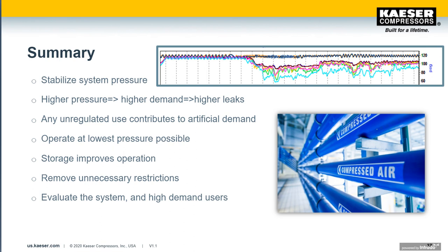Remember that pressure profile graphic that we showed you? Storage is not only going to provide you with better compressor operation, but could also provide you with better operation down there at the point of use. Remember that location of storage does matter. And if you have high demand events, addressing these individually will go a long way to optimizing your station.